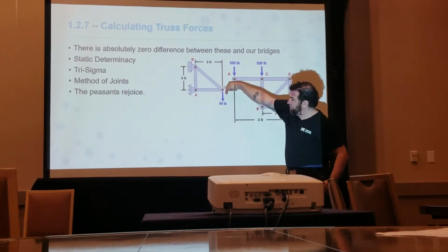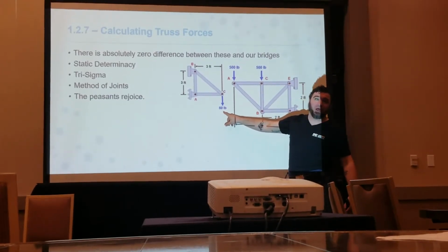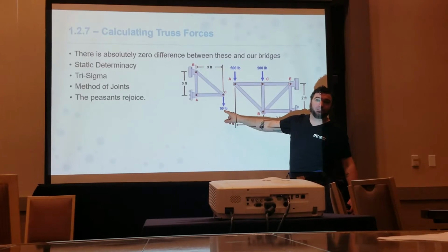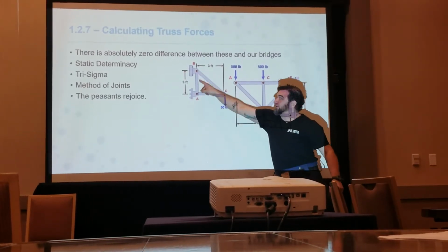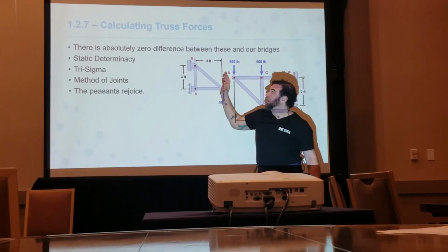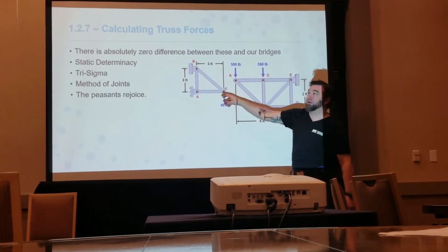So this is trying to induce what direction of moment? Positive or negative moment? Positive. Negative, I'm sorry. It's negative moment, because this is pulling down in Y to the right of our pin, so this is going to go clockwise.